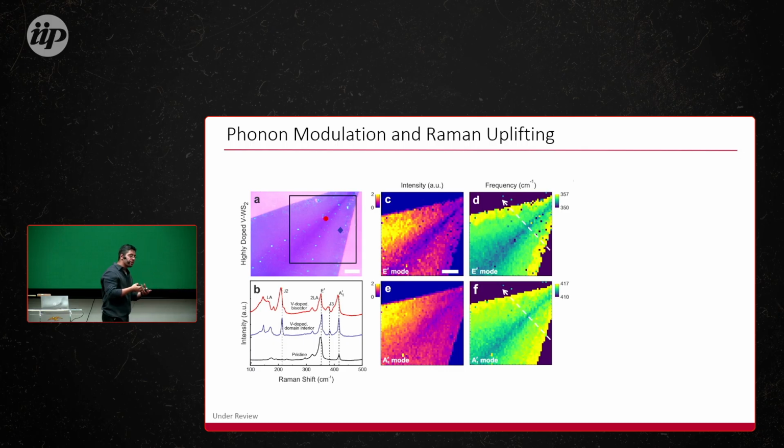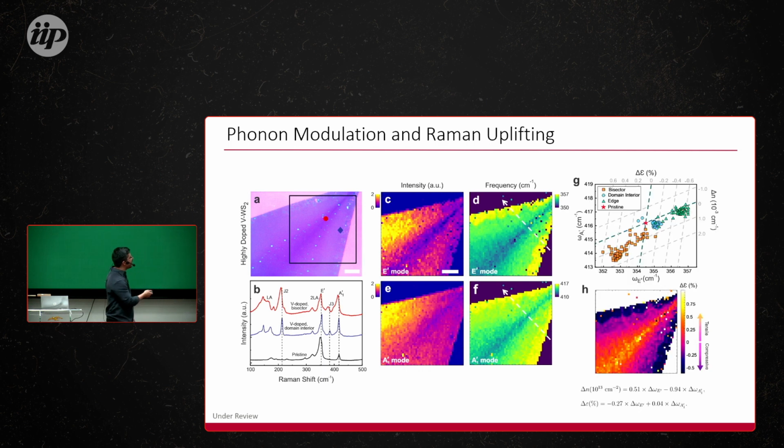And vanadium is much lighter than tungsten, right? So you would expect to have some kind of compressive stress. However, as I'm going to demonstrate, all the samples, especially along these bisectoral lines, demonstrate a tensile kind of strain. And the tensile strain that we observe over here is about 0.7%.